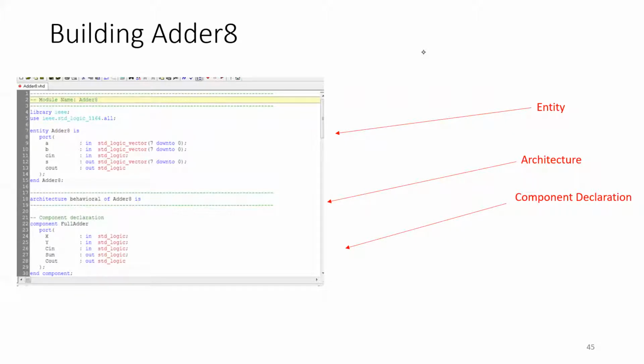Does the full adder component, when you type it out like that, is it recognized within the IEEE library? No, we haven't spoken about how to link them together. Oh, okay. I actually understand now what you mean. Even though you labeled your ports as vectors 7 down to 0, in your component declaration you're just assigning A to X and B to Y. That's correct. Okay, I understand now. Thank you.